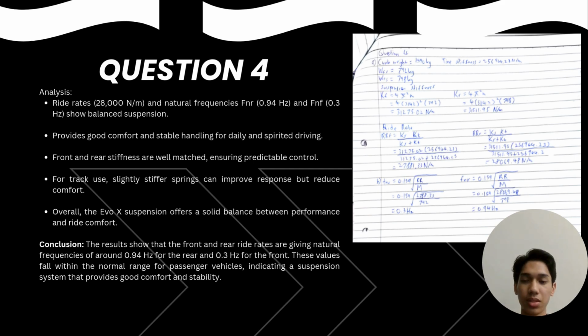Moving on to question 4, the ride rates, which are up to 28,000 Newton per meter, and natural frequencies at 0.94 Hz for the rear and 0.3 Hz for the front, show a balanced suspension.